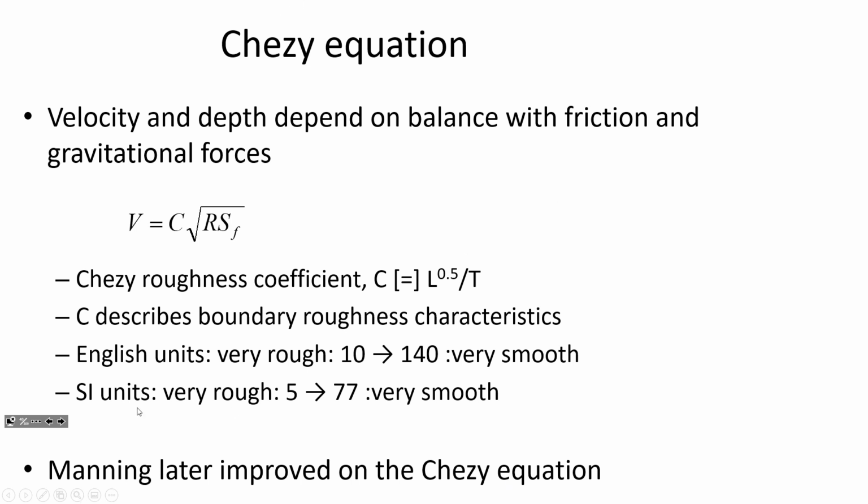So the Chezy and the Manning's equation both can be used in closed conduit flow. Manning's equation, though, these days is most often restricted to open channel flow. It's not often used in closed conduit pipe flow. So we'll use Manning's equation a lot in the second half of the semester.